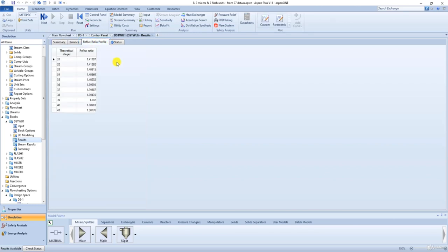Now, the principle of operation of distillation columns is beyond the scope of this course, but keep in mind that there is a trade-off between the number of stages and the reflux ratio. Each additional tray will add up to the equipment cost, while the increase in reflux will add up to the operating costs of the column. Now, we will use some of this information in our input for the DISTL column that we will cover in the next video.